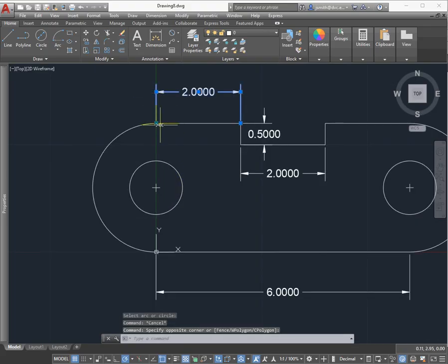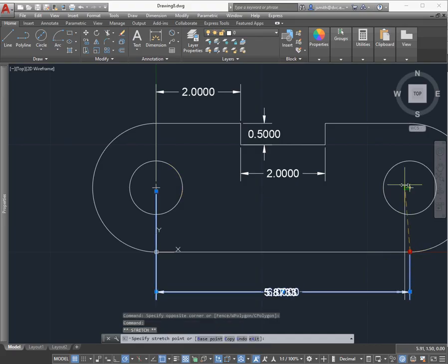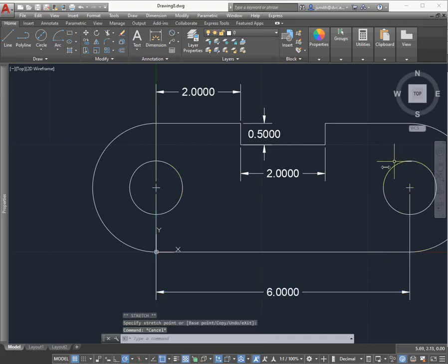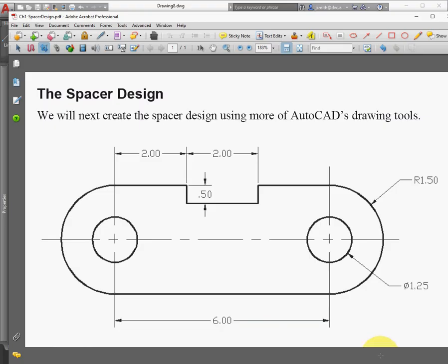All right, and then typically you need to have a gap there between that center mark. So if you put the dimension line on it, it's already defaulted in the settings. There should be a little gap there. So make sure you have a gap. This is showing a little bigger gap, but we're fine, just as long as that is not touching.